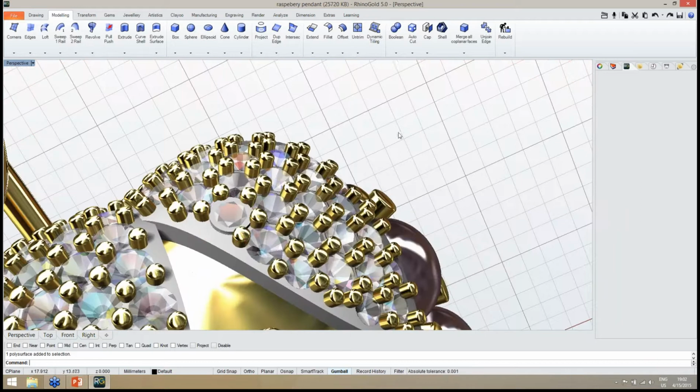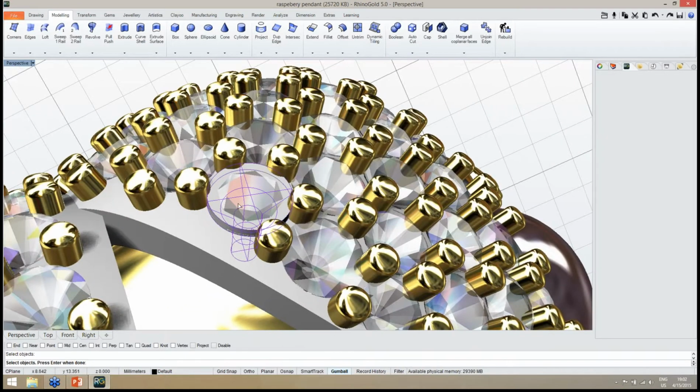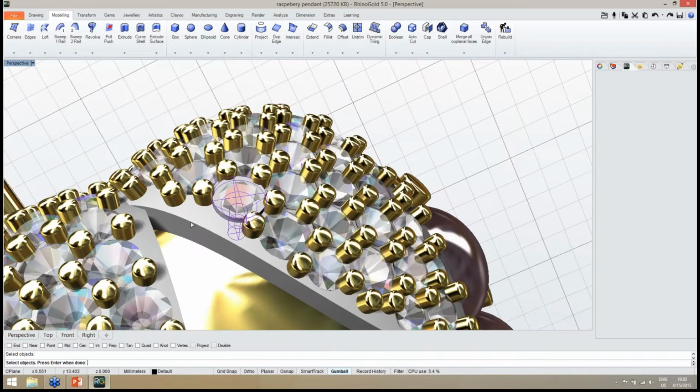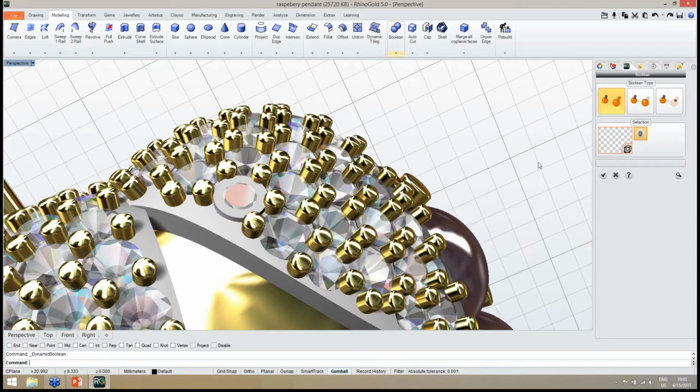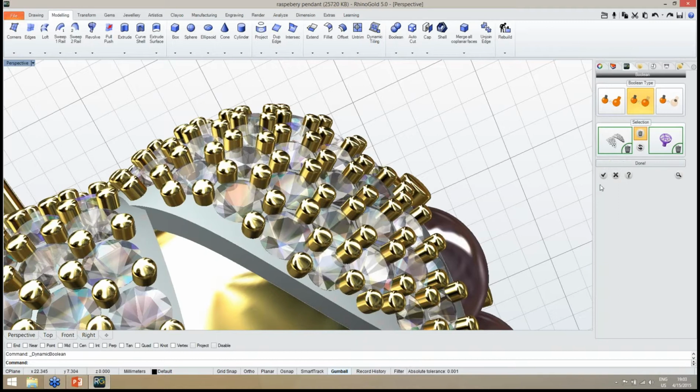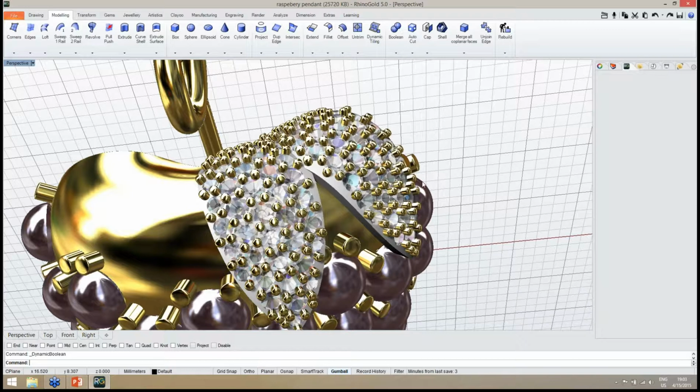So what we recommend is the option shake object. With this option, I need to select the objects I want to shake. In this case, I will select the cutter. It must be only one from the Boolean. It's not good if you select the leaf as well. So only the cutter, and we press enter. The tolerance in this case is 0.05, a very small distance. We are moving this object randomly just to try to avoid this Boolean problem. And I select now objects to keep, objects to remove, in this case the cutter, and I preview. So I'm going to try, and as you can see easily, I make this Boolean operation.